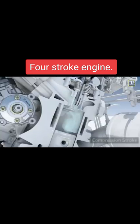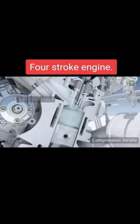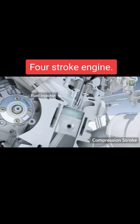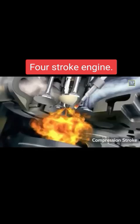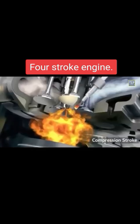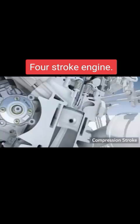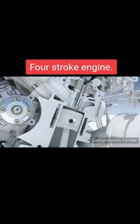Compression stroke. The piston starts moving up, the inlet valve is closed, then the air is compressed. The pressure and temperature of the air increase due to compression. Just before the piston reaches top dead center, diesel fuel is sprayed inside the cylinder. The fuel is sprayed by means of a fuel injector at a very high pressure, overcoming the pressure of the compressed air. The fuel gets mixed with air, which contains oxygen. Since the fuel is a hydrocarbon, the temperature of the compressed air is sufficient to initiate the combustion, and the fuel is burnt.